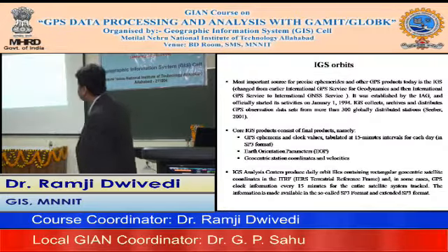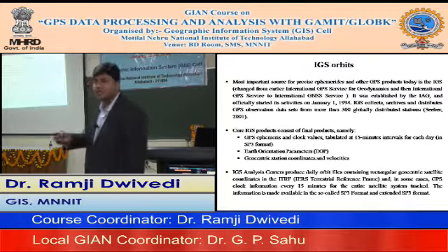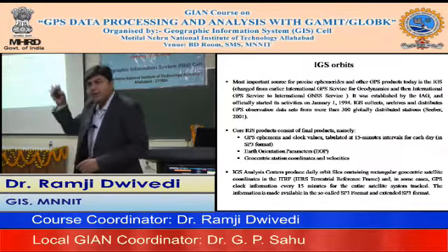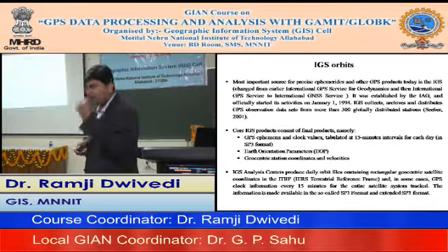The IGS orbits are nothing but the GPS ephemeris, with values tabulated at 15-minute intervals, in SP3 format.